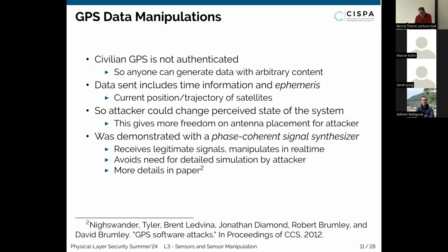There is, for example, one paper from 13 years ago where they looked into this. At least back then, this was definitely possible; you could do anything with this data if you wanted to. There was very little sanity checking being done in the GPS receivers. As far as I recall, they could send signals to GPS receivers that would then be used for location fixes where the satellites would be on the other side of the Earth, and the signals should never arrive at the receiver. There was no check for that.